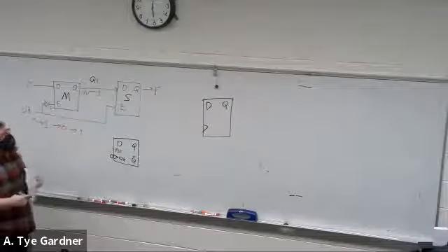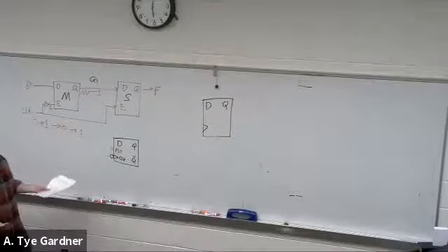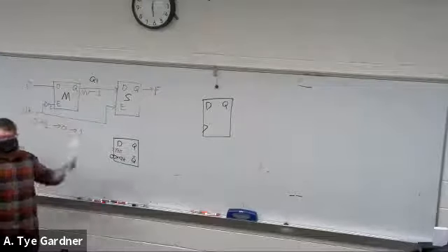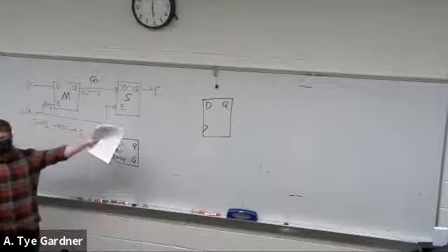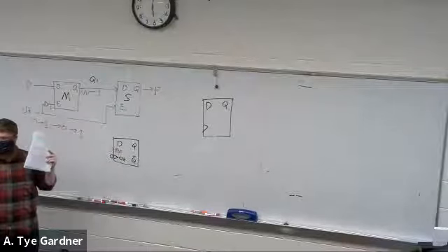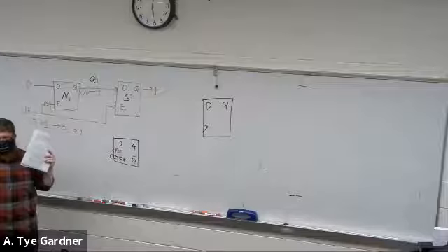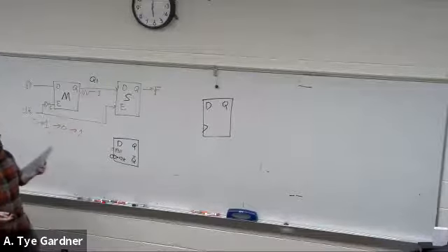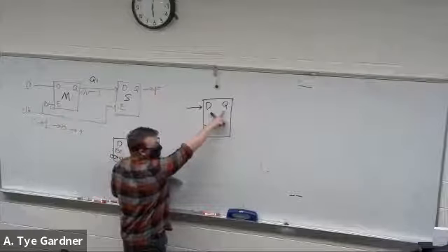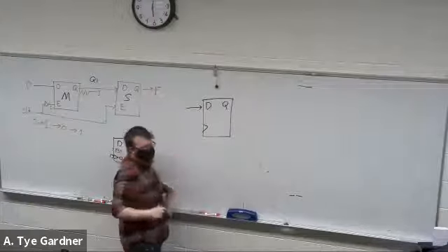There is a brute force way of doing it that we've talked about with enables before. Does anybody know how we could add an enable to this with minimal external circuitry? Phrased another way, I only want to clock D onto Q if enable.